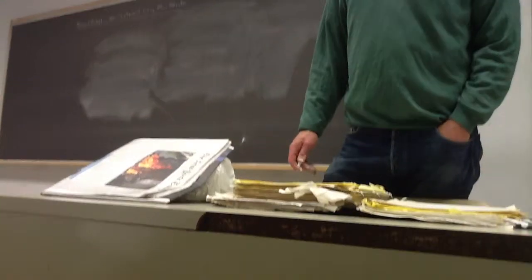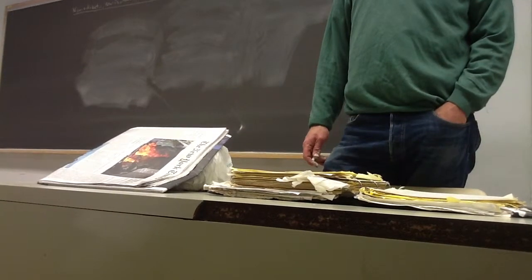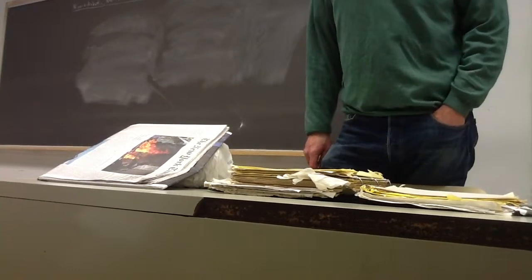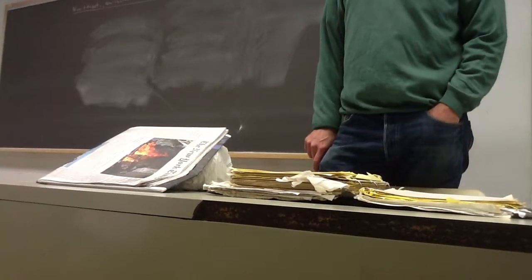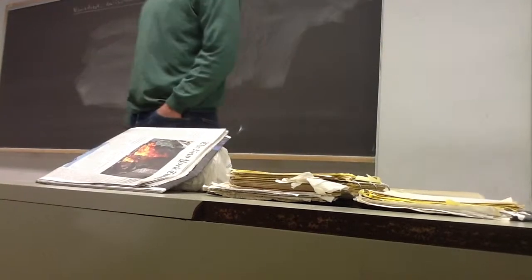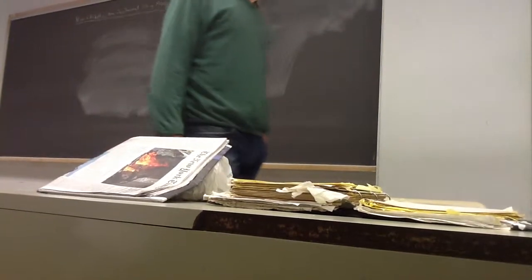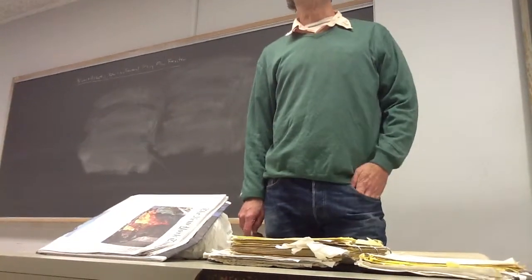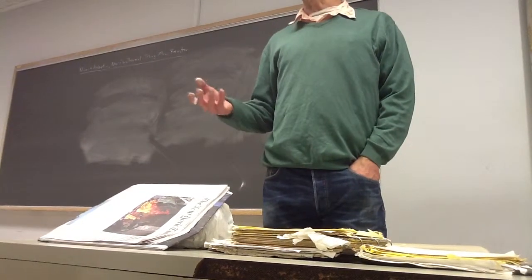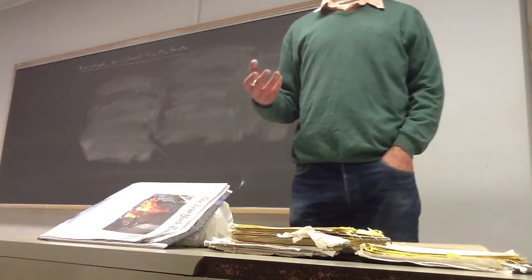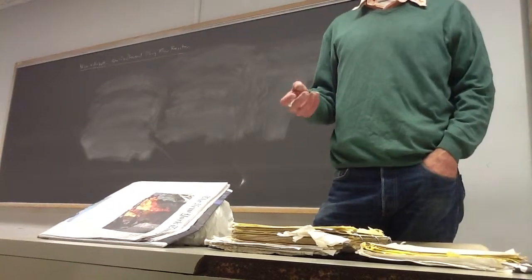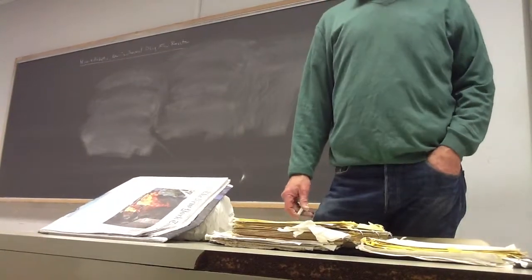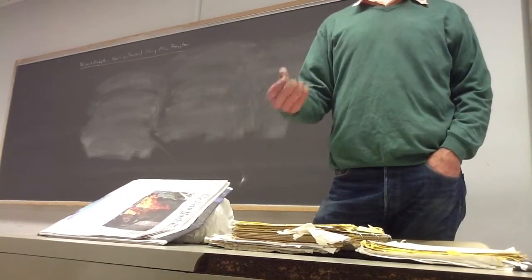The most common type of reactor that we use in many chemical processes, particularly in petrochemicals, is a fixed bed reactor. Now, there are more or less three ways of running a fixed bed reactor. In one method, you could keep it adiabatic. That is, you insulate the fixed bed reactor, and therefore the heat that's generated or consumed by virtue of reaction goes to either heat up or cool down the reaction mixture. And then clearly the temperature is a function of conversion.